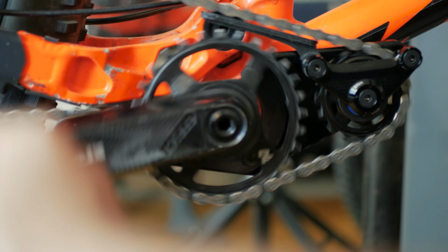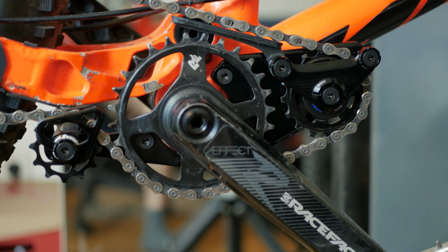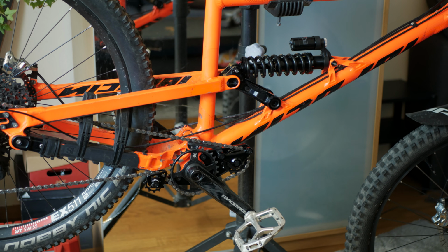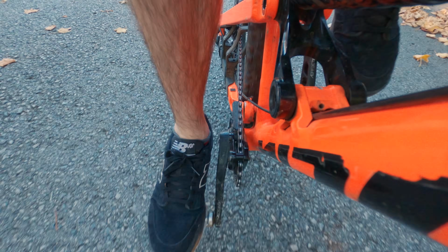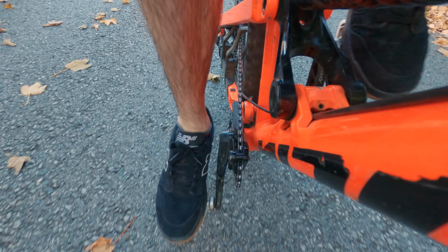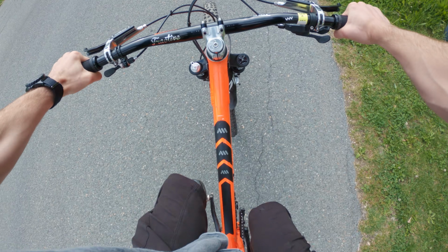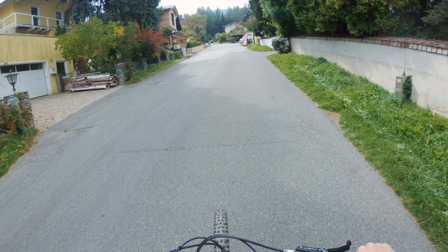The idler runs pretty smooth and the noise is barely noticeable under the crunching of gravel. However, a new behavior appeared with the new idler position that I never saw before on my previous mounts. Because of the chainline angle, the plate actually bends inward when pedaling in the largest cog. In the second and third largest cogs, the outward bending moment and the angled chain pull cancel each other out.